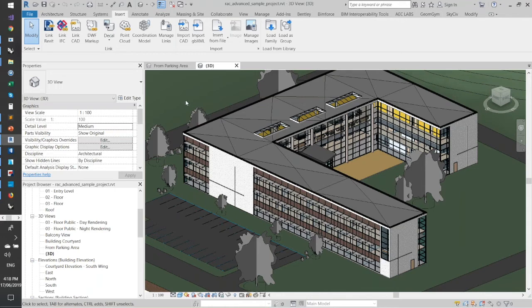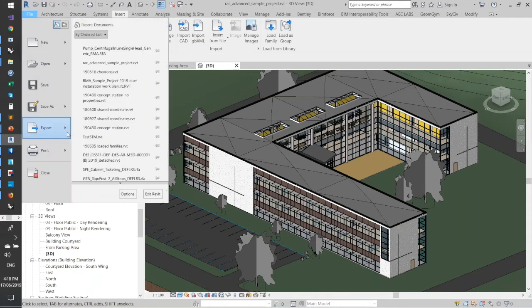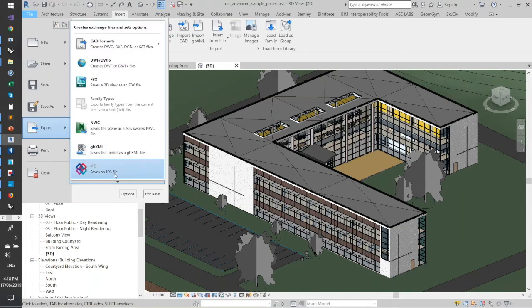So I've opened up the Revit application here, and I'm going to, as I said, touch quickly on some of the configuration around how you produce an IFC and how you can consume an IFC. So with Revit, and let's start with authoring IFC, you'll find that you access this or execute the creation of an IFC file through this Export IFC button here.